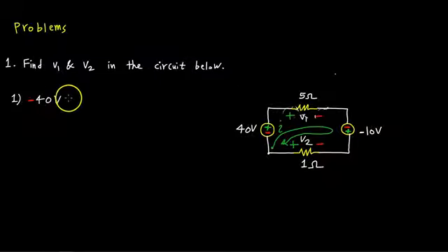And here's another problem. As we go through this, I'm going to point out the nuances and things to avoid headaches as you solve these problems. I think it's always best to label a voltage across a particular element in this manner, and then use that label to manipulate that variable. So for example, if you know there's 5 volts across this resistor, don't write that 5 volts into the equation. Use the variable so that if you're doing KVL, when you hit the plus side, you just say plus V1. If you see the minus side, you say minus V1.